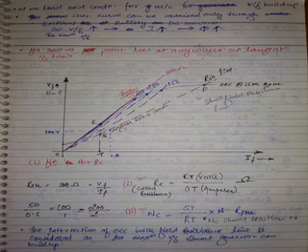Now, critical speed. According to the definition, it is the minimum speed below which the machine won't build up. Now let us consider this OCC is plotted for 1500 RPM. Let us assume like that. This OCC is plotted for 1500 RPM.